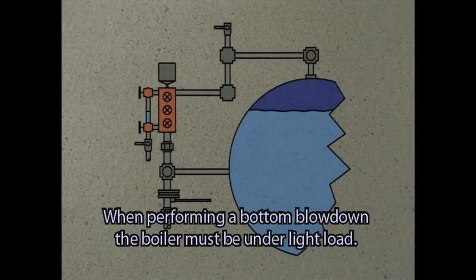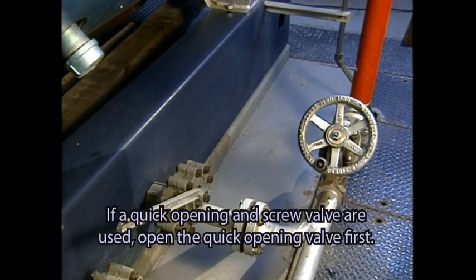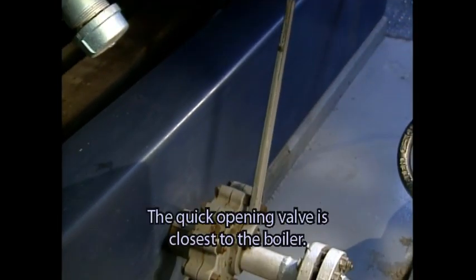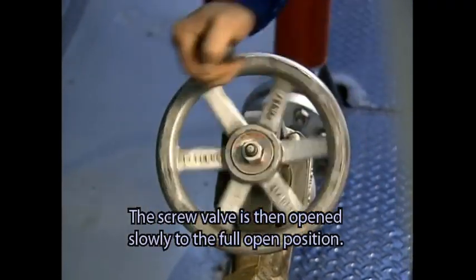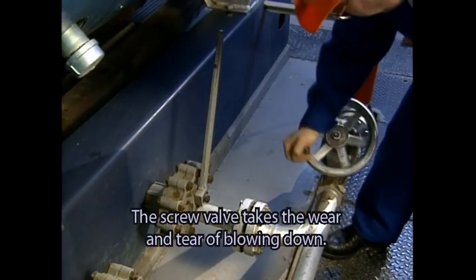When performing a bottom blowdown, the boiler must be under light load. The water level should be at the NOWL. If a quick opening and screw valve are used, open the quick opening valve first. The quick opening valve is closest to the boiler. The screw valve is then opened slowly to the full open position. The screw valve takes the wear and tear of blowing down.